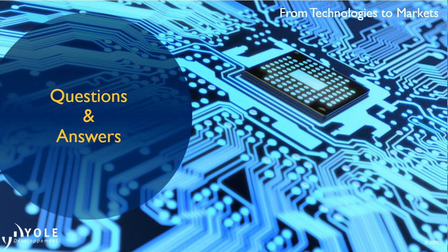Thank you. Good question. SRAM memory we already talked about, so I think the memory means DRAM memory. Samsung Foundry is ready to stack the DRAM memory on top of our logic, but what we need is a DRAM wafer with a TSV. So far, a lot of people have had technical challenges stacking the DRAM memory on top of a logic die because, from a thermal point of view, it is challenging to stack the DRAM die on top of a logic die. We have to solve all these technical problems first, and then later we can really stack the DRAM memory on top of a logic.